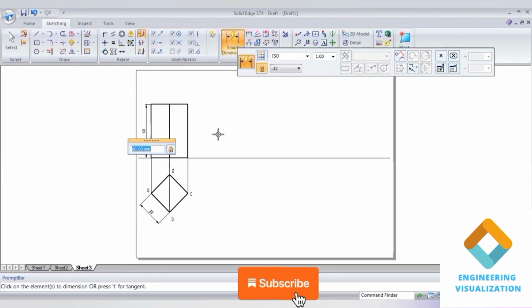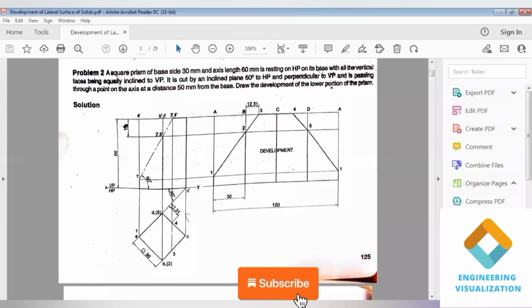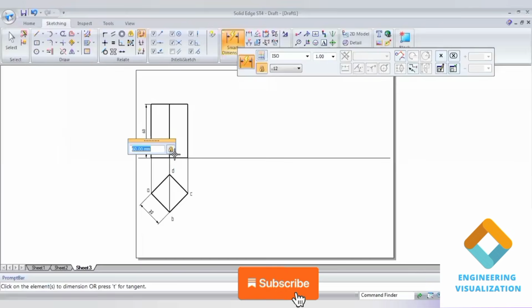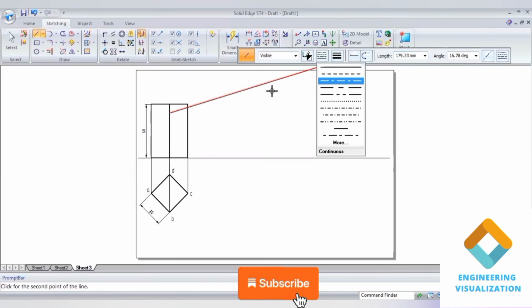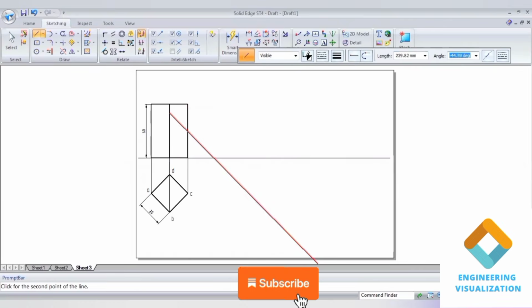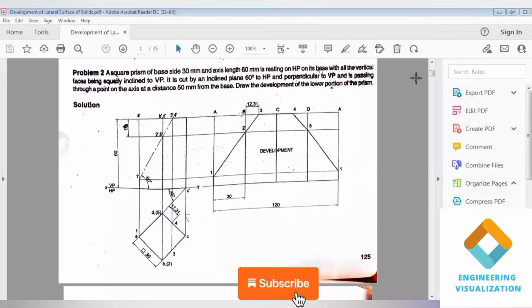Okay, so now we have to draw the section plane, which is at a height of 50 mm from the base. It is exactly cutting the axis at a height of 50. So I'll be drawing a 50 mm line from the base, exactly from the center on the axis. So go to line. From the bottom I am going to draw, that will be convenient. 60 minus 50 means 10, but I will be drawing from the bottom. So from the bottom, 50 mm length, I have drawn one line for reference.